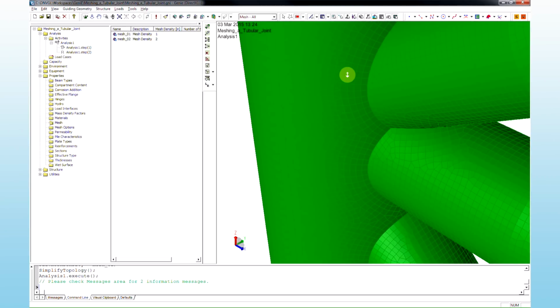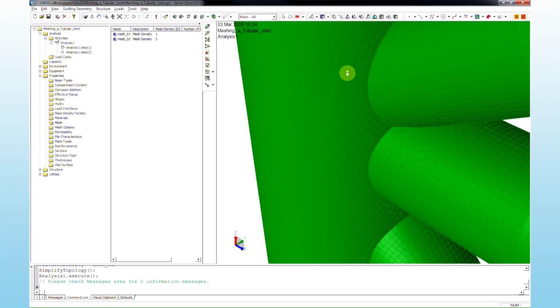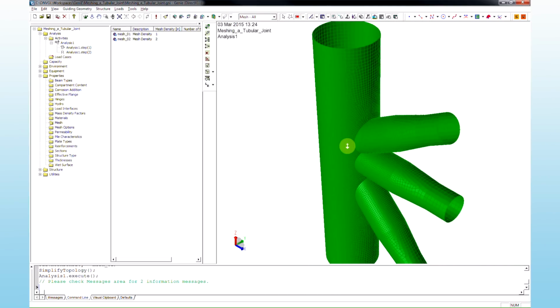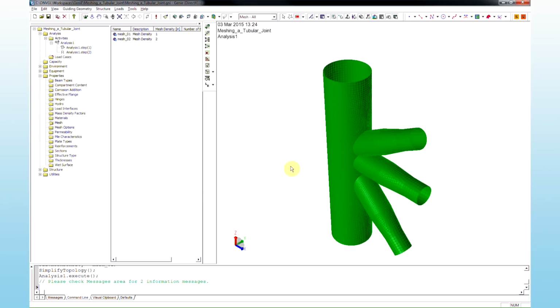In GeniE 7.0 or higher, there is another way to achieve exactly the mesh quality you need. With the new Edit Mesh functionality, we have now full control over the mesh all the way down to individual elements and nodes. Let's say we want to refine the mesh around the braces even more than we already did, except this time we will modify the existing mesh directly. All the according tools can be found here in the Edit Mesh toolbar.